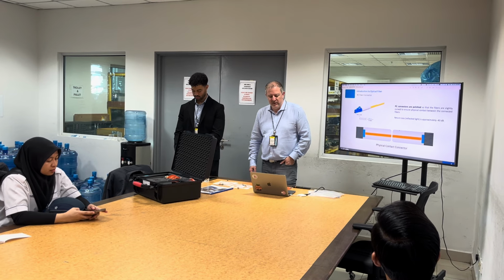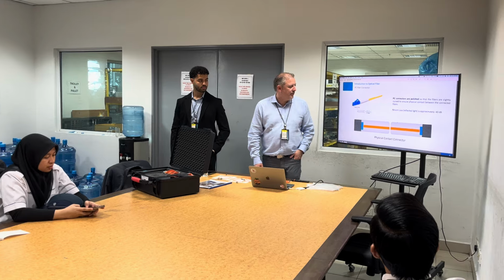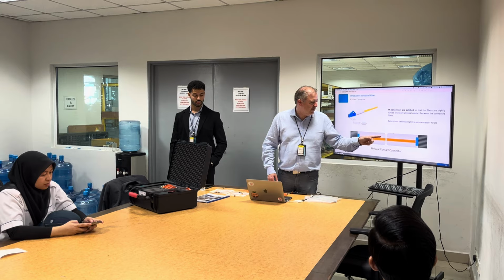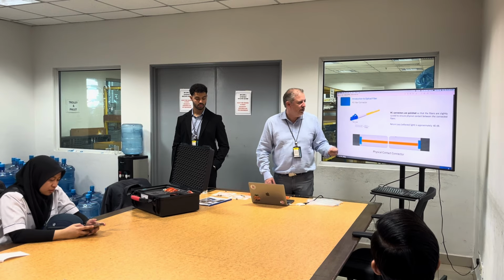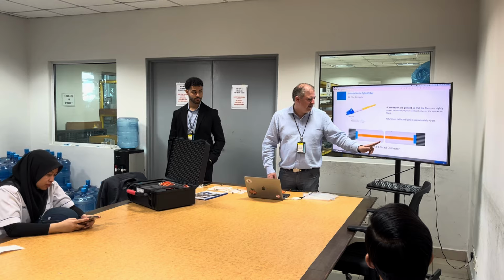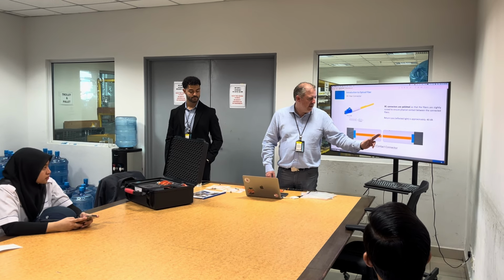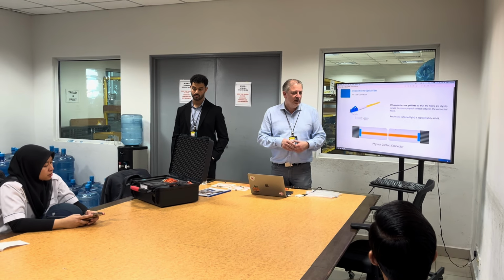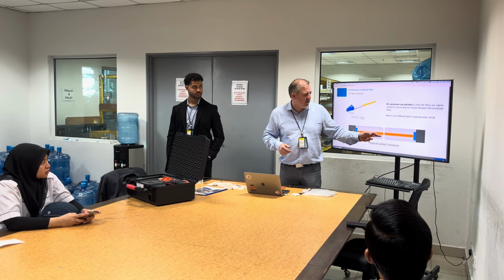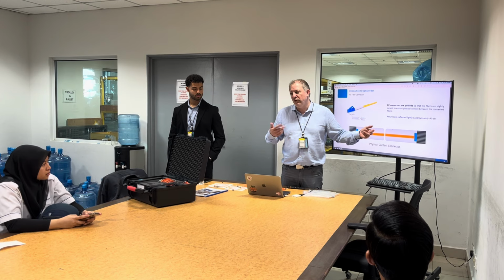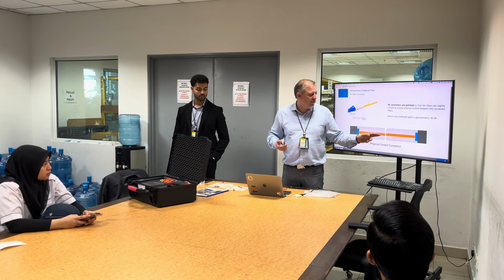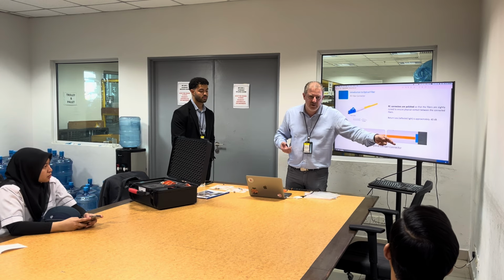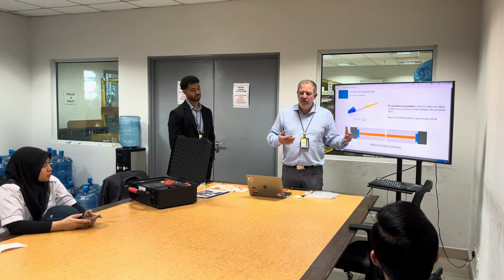So the way it works is that basically in a connector, you have a piece of fiber, another piece of fiber, with the core and the core, and what you expect is to get a physical contact between the two and a perfect alignment. That's the way you can transfer the maximum of light. If you have any misalignment, you're going to lose part of it, so you're going to have what we call insertion loss. If you don't have physical contact, you will possibly have high reflection. Some light will not cross, most of it will be reflected. So you have to ensure that.